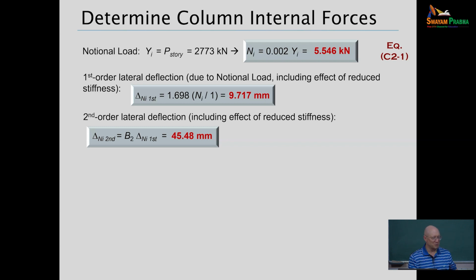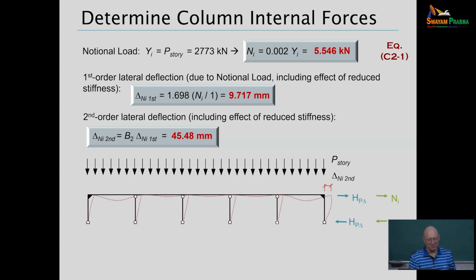And there are serviceability design considerations, of course, that we generally use in structures, but when it comes to satisfying strength, generally you could say, well, oh, the structure took the load, I'm happy. It worked. Okay? It may look like sin in terms of huge deflections, all distorted, but it took the load. We're good. Okay, now let me do serviceability and fix a few things. All right, and for these metal buildings, we're able to tolerate a high drift, so it may not be a problem. I'm going to work the amplified story drift method.